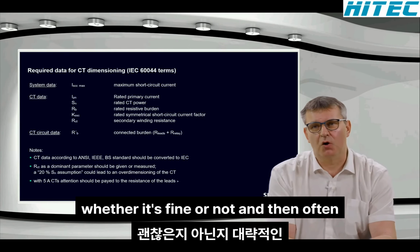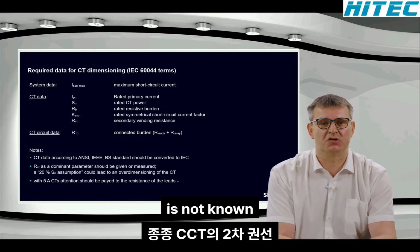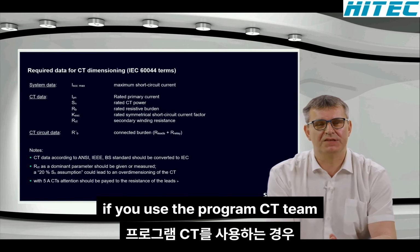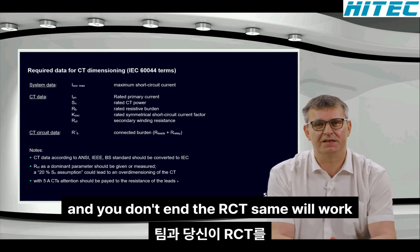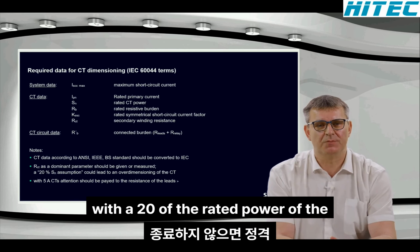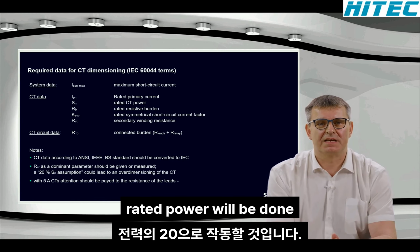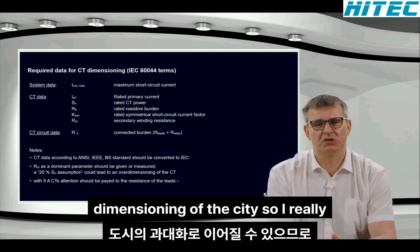And then often the secondary winding resistance of the CT is not known. If you use the program CT-TIM and you don't enter the RCT, it will work with 20% of the rated power. But this can really lead to an over-dimensioning of the CT.